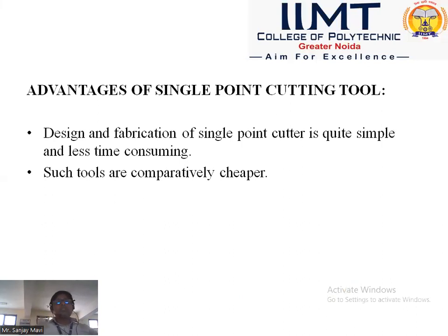Now come to the advantages of single point cutting tool. What are the advantages of single point cutting tools? The design and fabrication of a single point cutting tool is simple and less time consuming, because it has one main cutting edge.